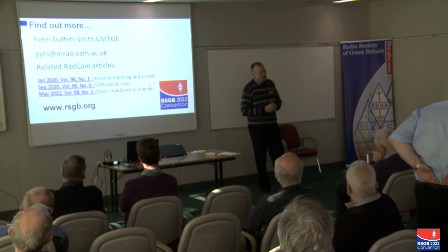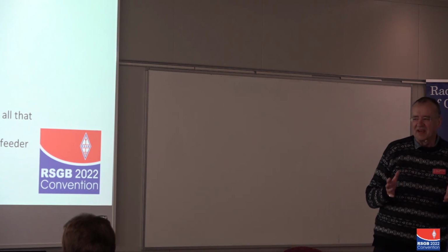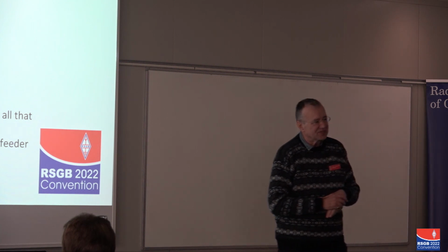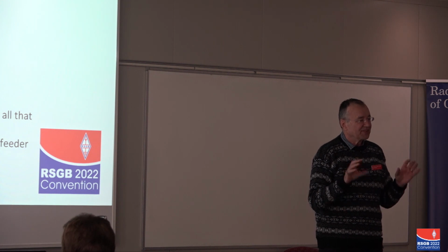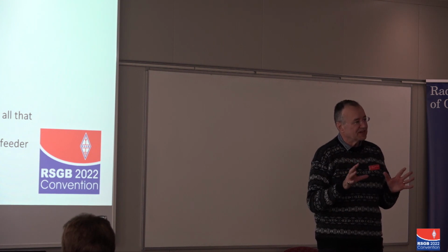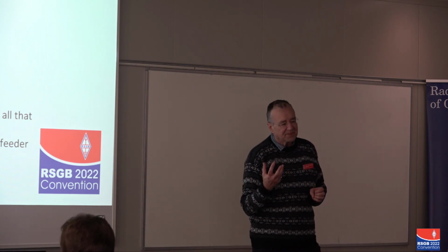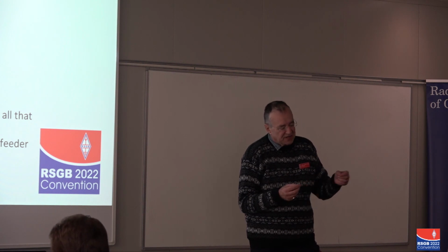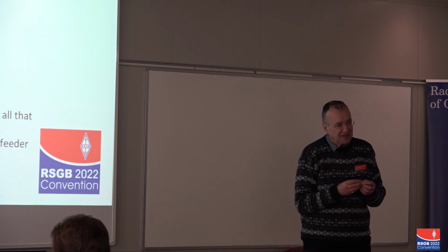No, you guess wrong. It is. There is this wonderful theorem. Well, it's called various things. I like to call it reciprocity. If you've tuned up everything correctly for transmission, then everything is tuned up correctly for reception. So if you have tuned your ATU so that it provides a 50 ohm match to your transmitter, then your receiver will also see the 50 ohm match.